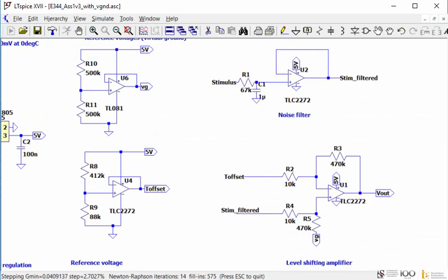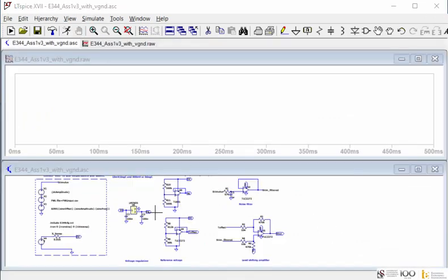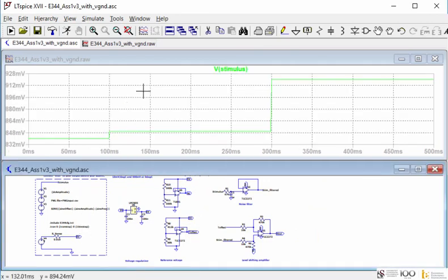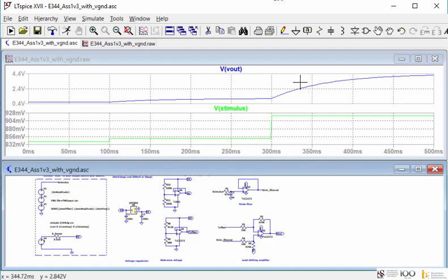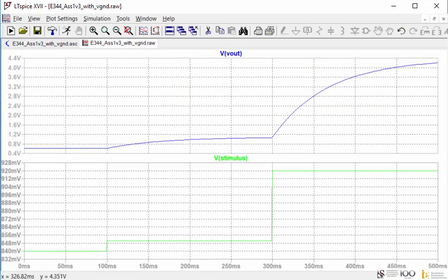So I'm just going to compile it again, and now it should compile a bit quicker. Right, so it's finally finished, and now I can just generate the stimulus again. So here's my stimulus signal, adding a plot plane, and over here I'm just going to plot V out. There we go. So let's have a look at whether this then meets the requirements. So as you can see, this has settled, and it has settled at, let's have a neat look deep inside.